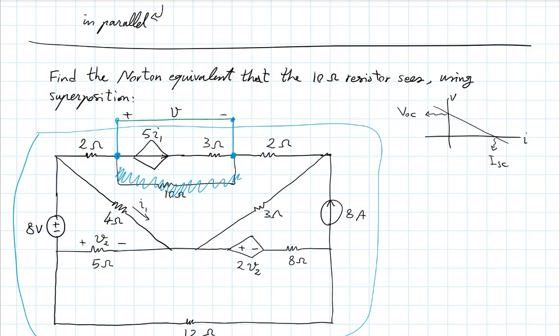So now the voltage there is going to be 0, and you're interested in the current going through this wire. Which way should I indicate the direction of this current to be? So remember, this is how I had defined my voltage. Right? So now I have set the voltage to 0, and I want the current, because I'm after a Norton equivalent. So I want the short circuit current. Which way should the direction of the current be?